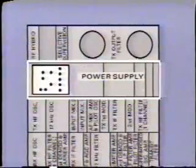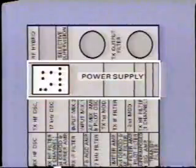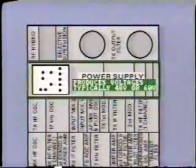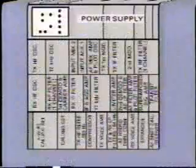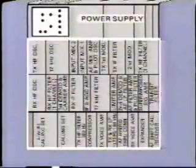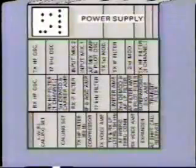The second tier of equipment is devoted to power supplies for the carrier. It contains modules to filter or condition the incoming power, as well as modules to produce the special voltages needed by the electronics, typically 48 or 60 volts, and also a minus 15 volts. Moving down the carrier panel, the next three tiers contain the modules that make up the radio part of the carrier, both transmitter and receiver.